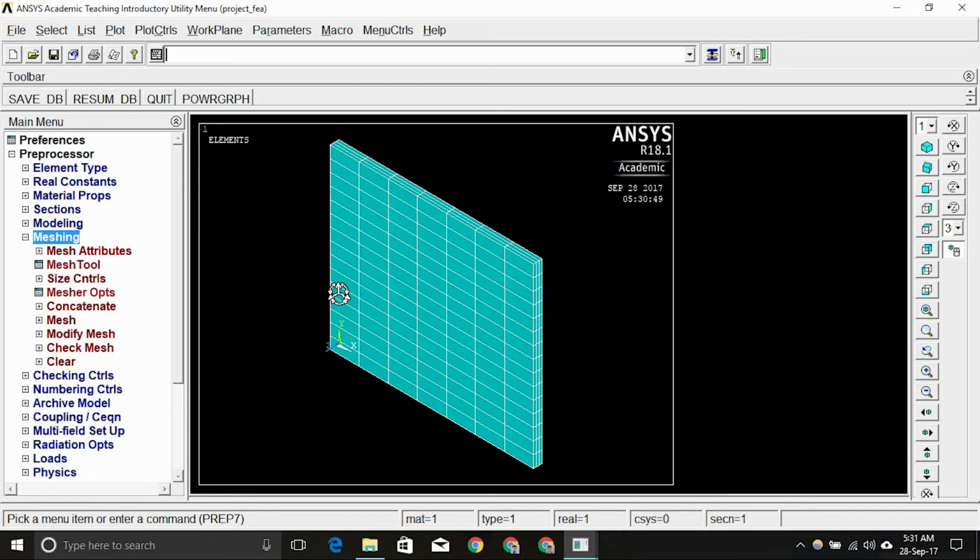So it is better always to apply our loads, not usually in the case of thermal, but in all other cases like the static structural cases, on the key points rather than the nodes. This is because say you did meshing, you solved everything and took the results, and you were not satisfied with the results because of the meshing, and you want to go back and remesh it.